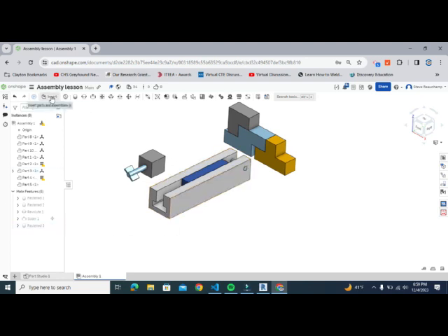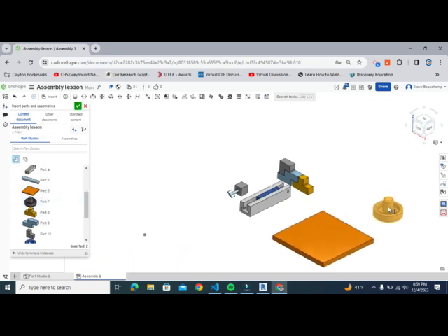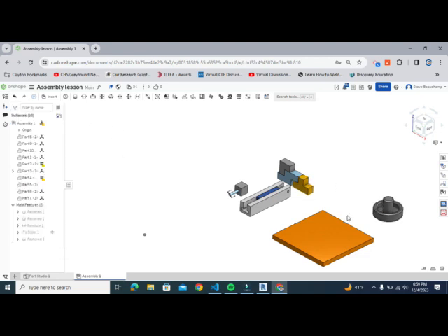All right, moving forward. The next parts that we're going to take a look at are parts 6 and 7. So we'll just place those out here. And once we place those out here, we'll hit the green check. And then we're basically going to take what looks like this air hockey puck, and we're going to put it on this surface, and we're going to make sure that it can move freely on the surface, but that it can't leave the surface. We're going to do that using the planar mate.